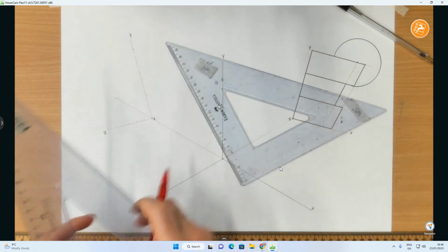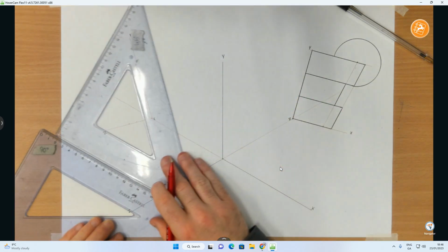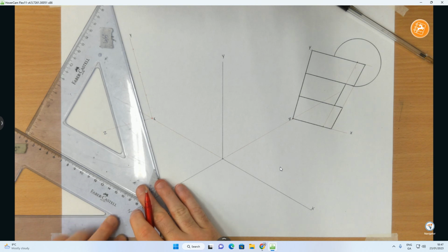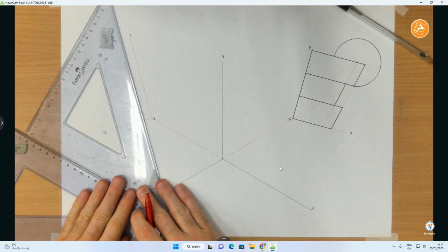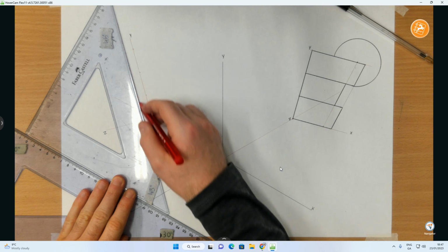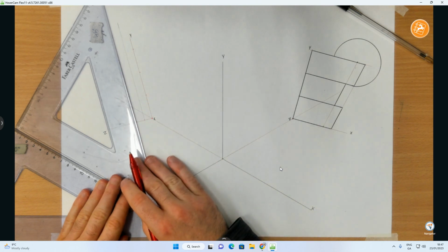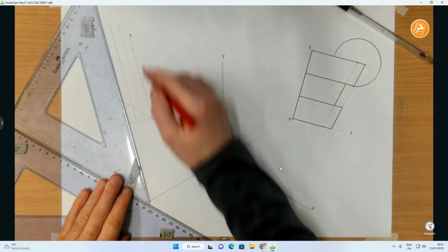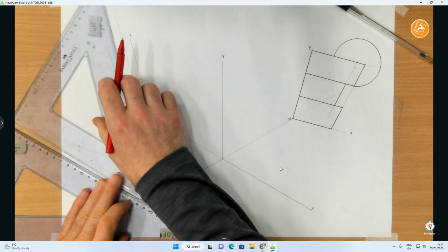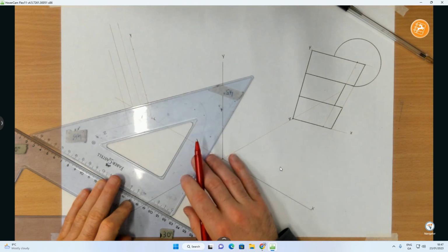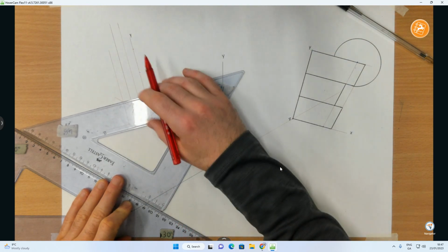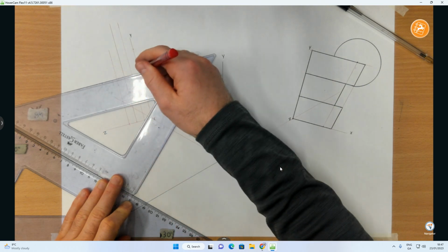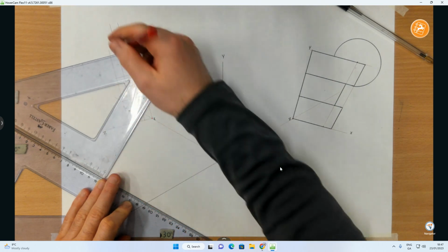And now using the same principles that I've just learnt, so there's that one there together, 30, 60 degrees set square. So this one's actually going to go, I'm going to extend this one a little bit higher, because that's the one that's going to contain the circular portion. This one only needs to go up to about here. And then if I rotate this one on the set square, I can now go horizontal. I should say inclined at 15 degrees.